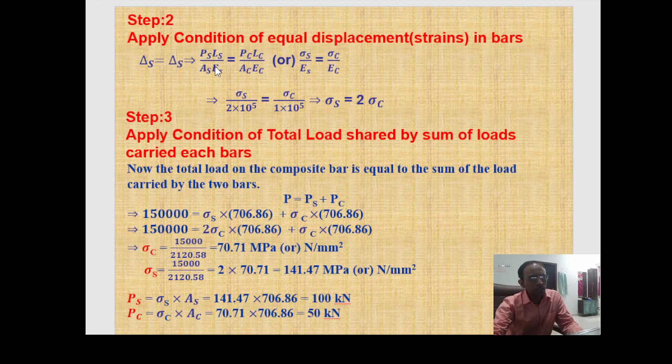So here, applying the equal displacement condition first is easy because we get to know all the values, because the lengths and the E values are known to you.